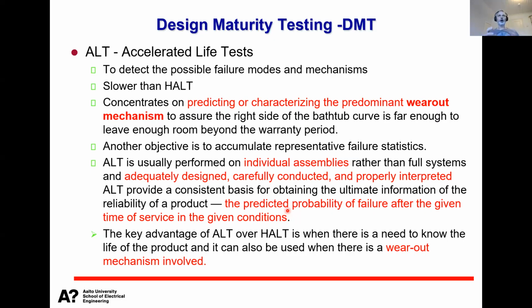So we don't test the whole product, we test parts, and we can even test one specific component, and it could be a kind of test design. It does not have to be that the component is assembled in the actual motherboard, but we could have a test board, for example, containing 15 of those components, and we can test 15 of them simultaneously if we are sure that the stress condition is correct.